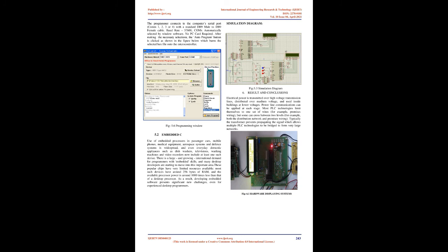Preload programming software. Preload is a software working as a user-friendly interface for programmer boards from Sunrom Technologies. Preload gets its name from the term program loader, because that is what it is supposed to do. It takes in a compiled hex file and loads it to the hardware. Any compiler can be used with it, assembly or C, as all of them generate compiled hex files. Preload accepts the Intel hex format file generated from the compiler to be sent to the target microcontroller.